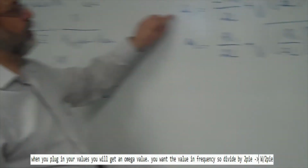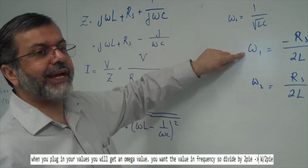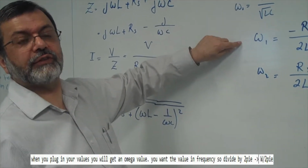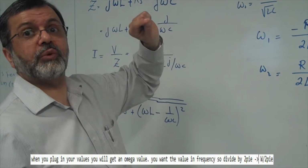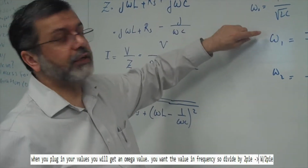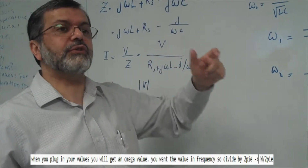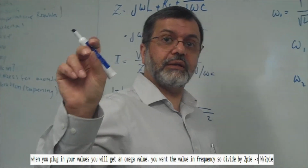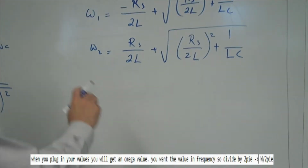So let's say you get 1,000 in here. I'm just throwing this in. So 1,000 is 1,000 radians per second, so you have to divide this by 2 pi. 1,000 divided by 2 pi. Pi is 3.14159, not 180. So you're going to say 1,000 divided by 2 times 3.14. That gives you the frequency, because in the scope you don't see radian frequency, you see hertz. So these are the two.